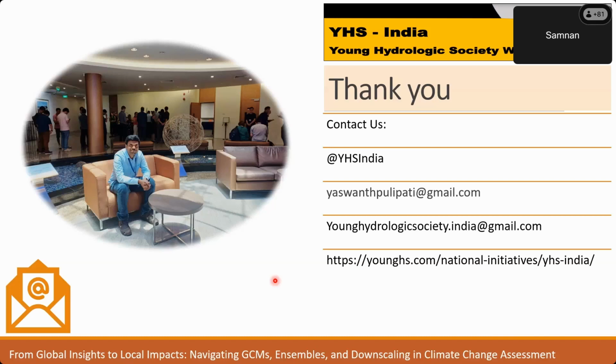Here I would like to bring 2 points. A GCM which is not performing for the past, we should not consider, as it may not give reliable future projections. But even then, if you want to minimize the number of GCMs, you can do distribution comparisons, as I have shown with some CDF comparisons. You can use error metrics on a climatological basis, monthly or daily, such as root mean squared error and the correlation coefficient, to understand the errors in the GCMs. And essentially you can give weightages to the GCMs.